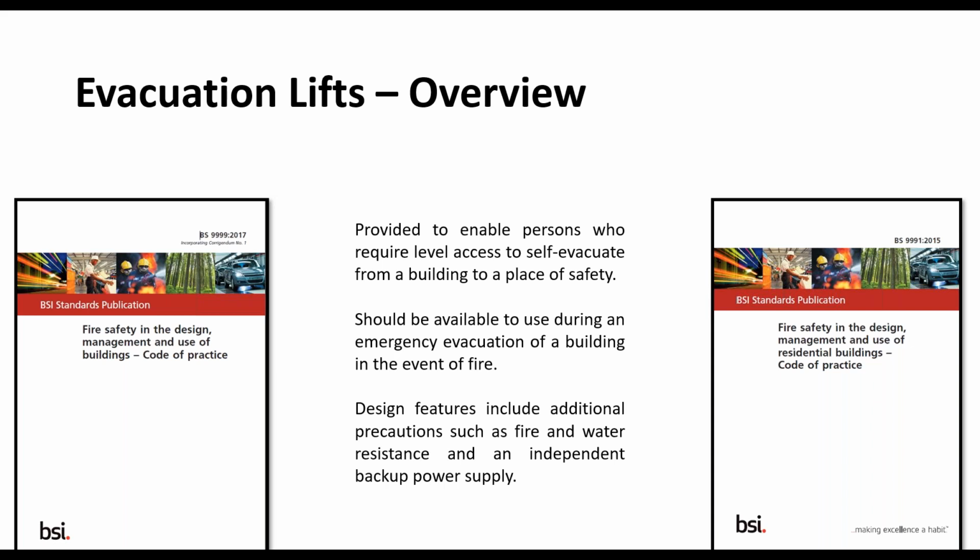And if we think about, again, the very specific nuances between managed and unmanaged settings, we are, I'm sure, acutely aware of the separate challenges that arise when we consider those specific scenarios. We also know that evacuation lifts should be available to use during an evacuation scenario when the building has entered into an emergency evacuation phase, and that some high-level features that we associate with evacuation lifts include additional precautions for water and fire resistance and independent backup power supplies.